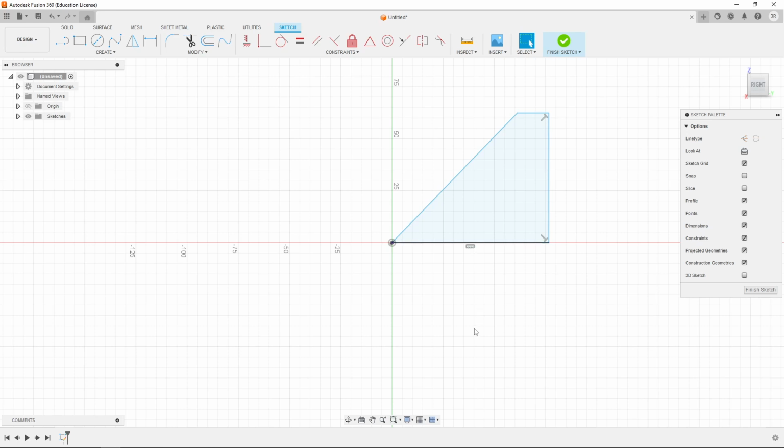The way you know that a line or shape is what we call fully constrained, locked in place definitively, is the color changes. This line is black. This line cannot be moved in any way. These other lines happen to be a light blue, and that's because they can be manipulated in some fashion. In fact, I can grab this vertex, for example, and drag it. You can see those lines change, but that black line does not change, right?